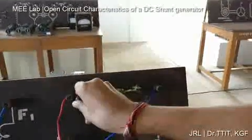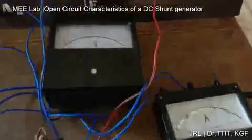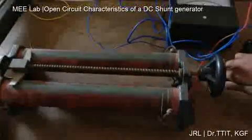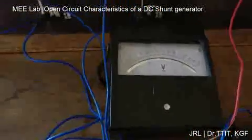Now there is a switch which is connected to the 750 ohms rheostat. So we need to close this SPST switch. Now we need to start varying the rheostat little by little and take down the readings. When the rheostat is brought from cut-in position to cut-out position, you can see the gradual build-up of the voltage little by little.